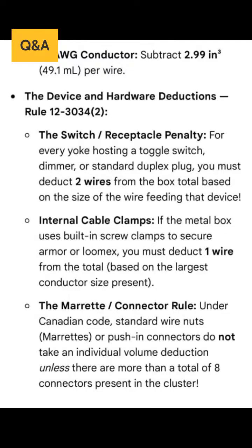Internal clamps: if the metal box uses built-in screws, clamps to secure armor or romex, you must deduct 1 wire from the total based on the largest conductor size present.